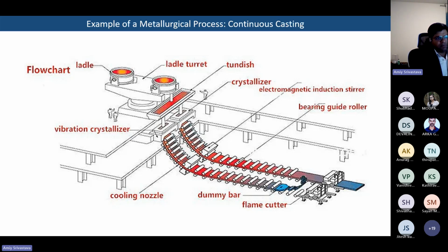Firstly, some people have a direct reduced iron furnace, or DRI shaft furnace, Midrex, Corex, and so on. And some people have a blast furnace. We get hot metal from the blast furnace, and it goes to the primary steel making station. There we can have an electric arc furnace or a basic oxygen furnace. Very old-timers, those who were working in Steel Authority of India Limited, ArcelorMittal, Tata, or Stelco, might know the open hearth process as well. But that process is completely extinct, obsolete, these days.